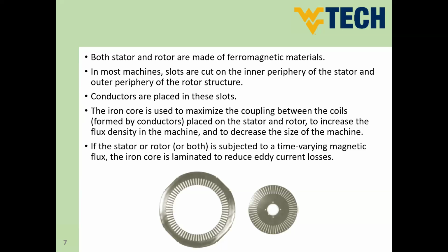So if we have a sheet, and for sure this sheet will have insulation, just on one side, okay, and we call it laminated sheets. So if we have the sheet and start punching the sheet from inside and having the slots inside, this now will represent the stator sheet. So this is one sheet of the stator right now.